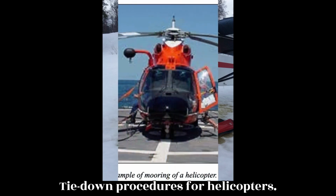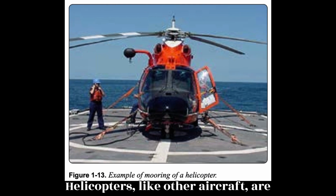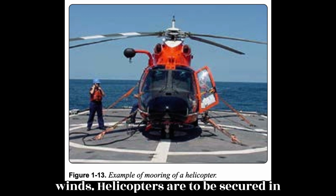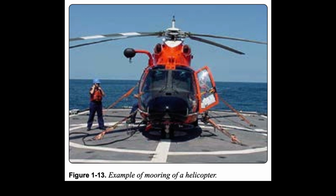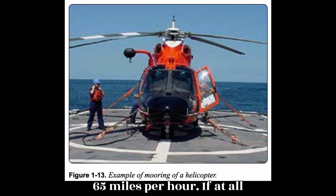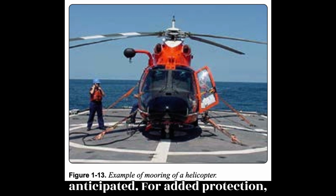Tie-down procedures for helicopters. Helicopters, like other aircraft, are secured to prevent structural damage that can occur from high-velocity surface winds. Helicopters are to be secured in hangars, when possible. If not, they must be tied down securely. Helicopters that are tied down can usually sustain winds up to approximately 65 miles per hour. If at all possible, helicopters are evacuated to a safe area if tornadoes or hurricanes are anticipated.